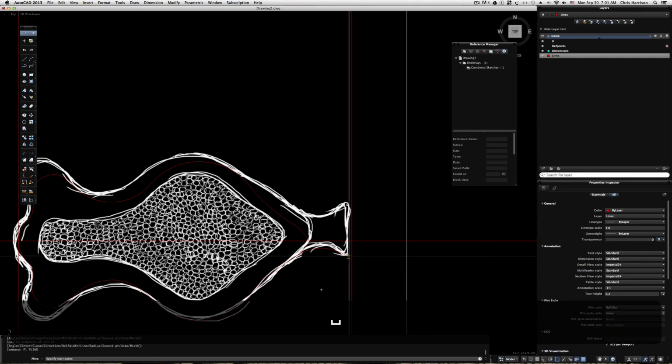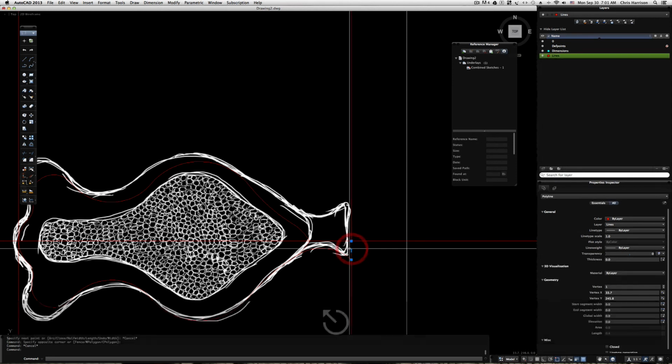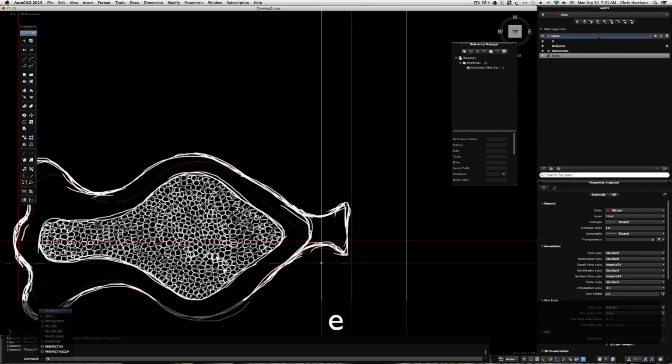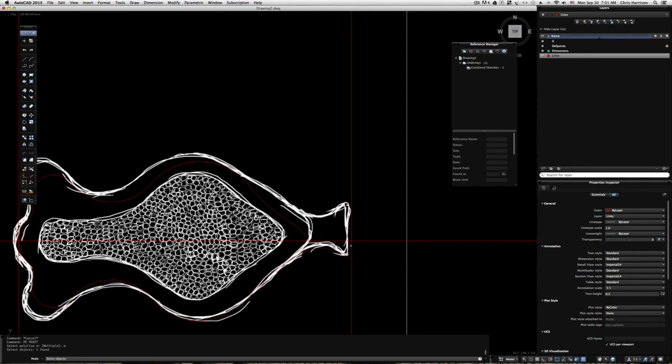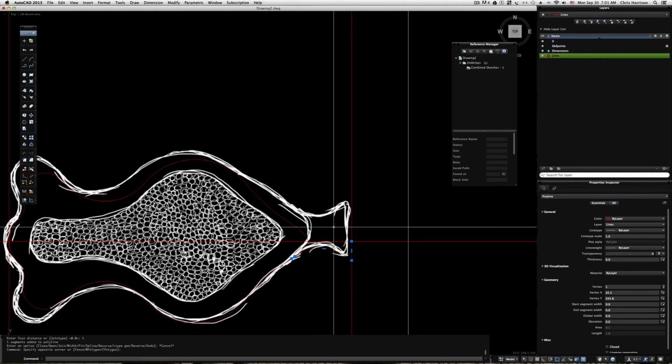And actually, let me go back in there and draw another line straight up. Now I drew these lines as two separate pieces, and I don't want them to be. That's not really clean. So I'm going to join them. I'm going to fuse them by doing P, E for polyline edit, enter. I'm going to hit M for multiple. I'm going to select that line and that line that's sitting on top, enter. J for join, enter, one, enter. And now they should be a one line segment.